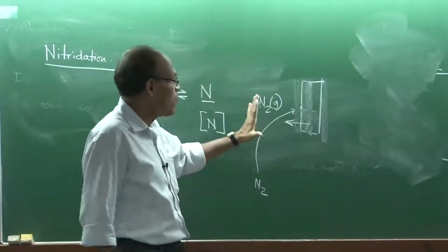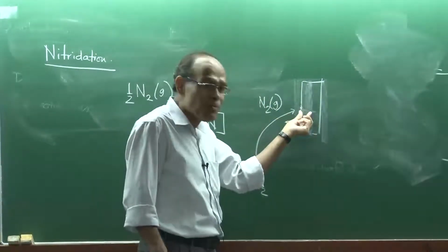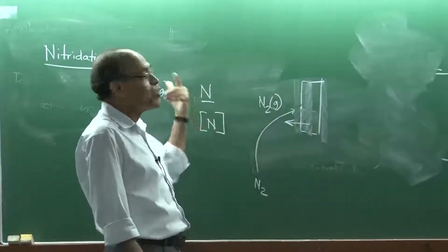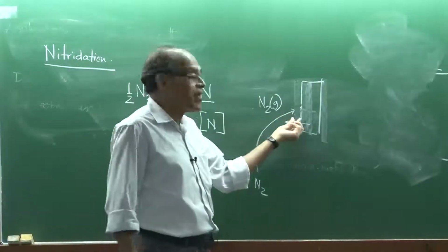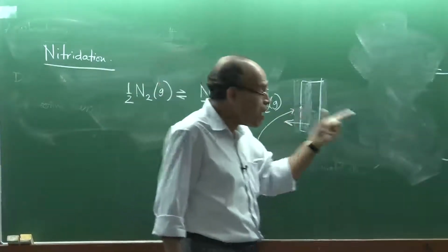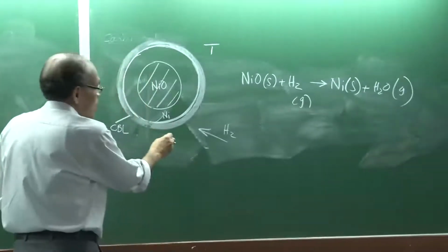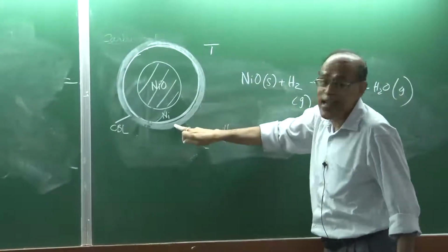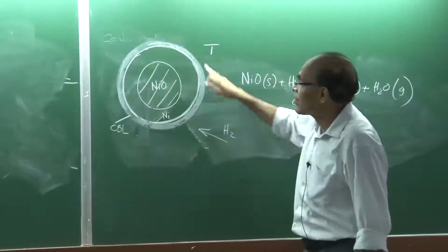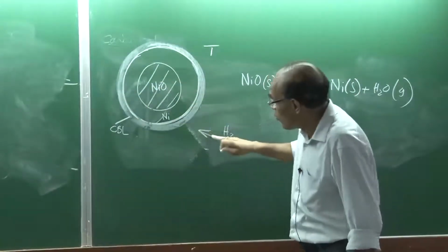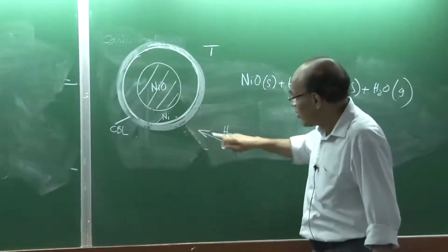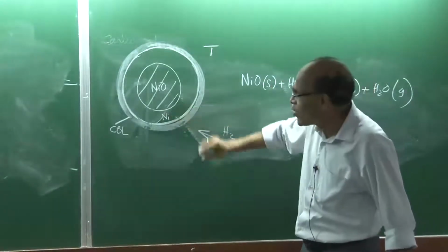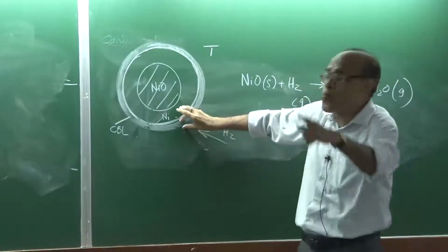But in this kind of problem, because solid state diffusion in a dense material is extremely slow, and there is no product gas, it becomes a futile exercise to consider a boundary layer resistance. But particularly when you have a product gas coming out, there could be high product gas concentration here, which will cause a gradient of hydrogen from here to here, and therefore this can afford some finite resistance. So it may not be a good idea to ignore boundary layer transport altogether